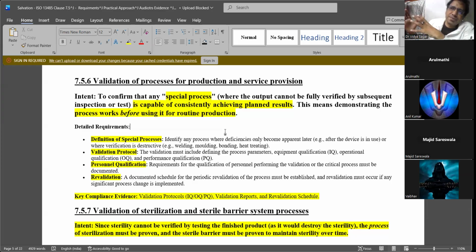What validation means is if you use the same machine with the same process parameters and the same material, I can assure you statistically that 99% of the time, or even if 95%, with a probability of 95%, you will get a tube with an ID of 0.2 mm.